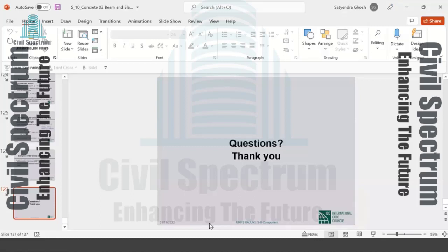Okay. So what is the minimum shear reinforcement diameter that we try to meet? The minimum shear reinforcement diameter is number 3, which is 3/8 inch, so about 9 millimeter. Yeah, 9 or 10. Yeah, that would be the minimum.